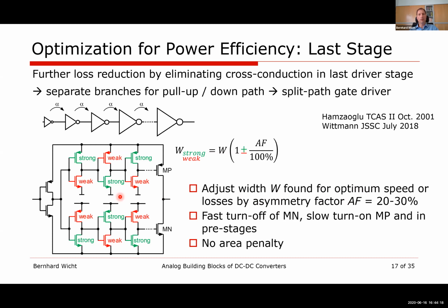What we get from it is that the turn off activity always happens before we turn on the other transistor, and it doesn't matter which polarity, it always works. So you can simply follow the turn off and turn on path, alternating here to keep the signal properly aligned. That's a nice implementation, because it also tracks process variations quite well.